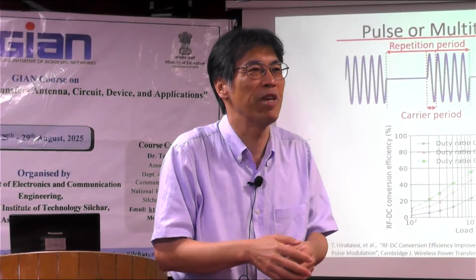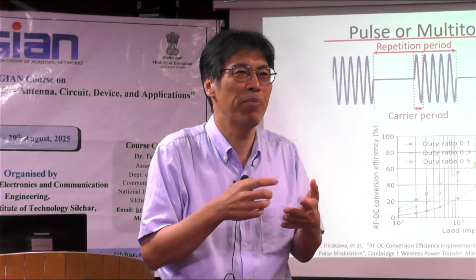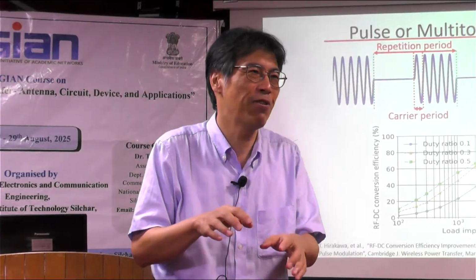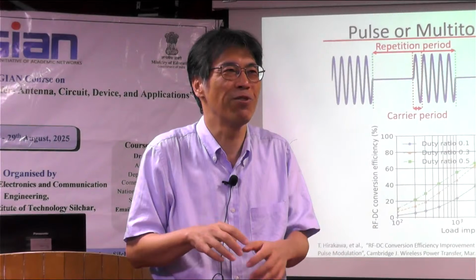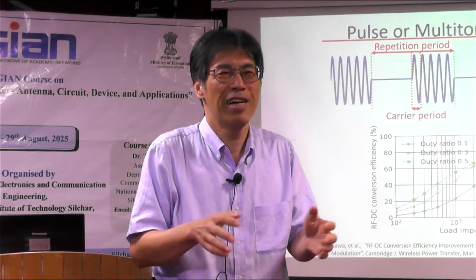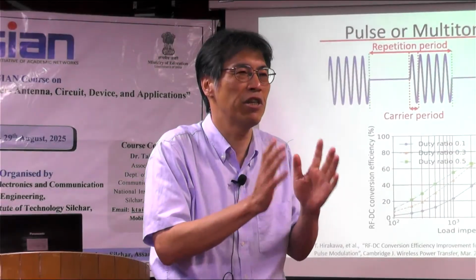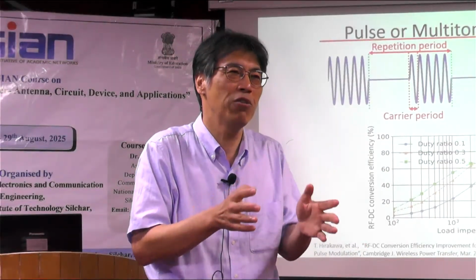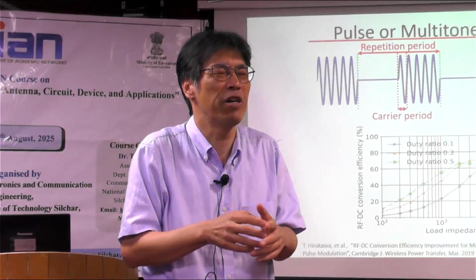A new diode is better. We tried, for example, a rectifier with a PIN diode or normal diode, etc., very long time ago. But the PIN diode, we cannot use it. Or, for example, a silicon carbide diode. Of course, with any silicon carbide diode, fT or fmax was not enough, so efficiency was very poor.